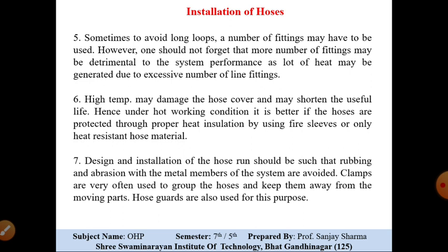Abrade means rubbing. The pipe is touching some surface, and due to the motion of the arm the pipe is slowly being rubbed over some rough surface. That surface will slowly deteriorate or remove the upper layer of the hose, decrease the thickness of the hose pipe and reduce its life. So it's very important to keep in mind that the hose pipe should not be installed such that they rub against each other or abrade against some particular metal member.